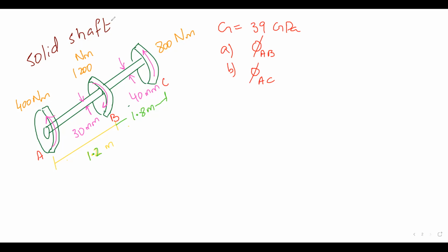But in this angle of twist formula, phi equal to TL over GJ, the T that you're talking about is the applied torque. I won't have a reaction. If I am twisting, the torque that I'm applying shows up in the formula, not some fictitious reaction. Are you getting my point? Something very minor, by the way, you wouldn't have even noticed, but anyways.